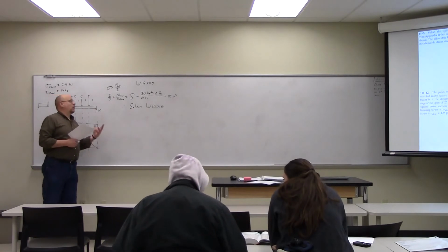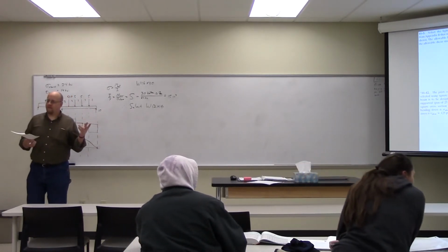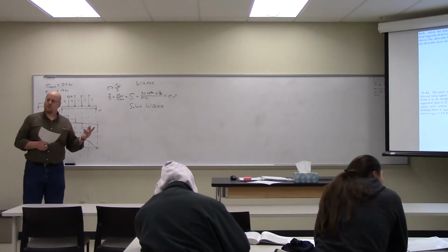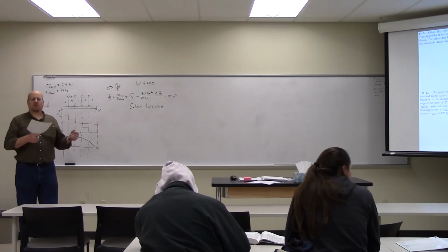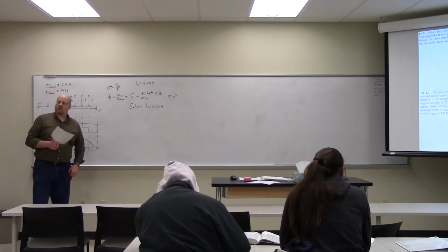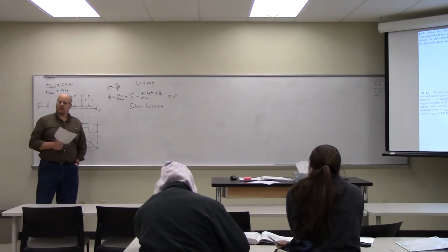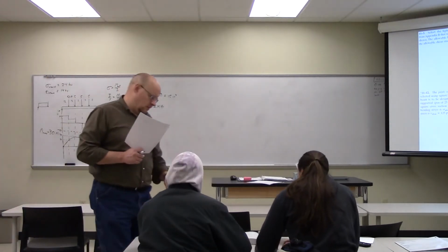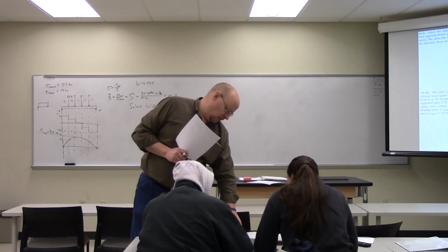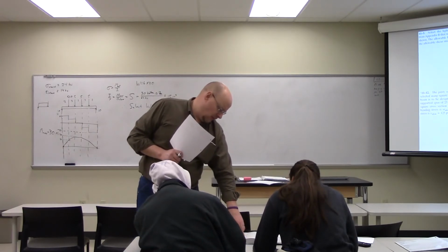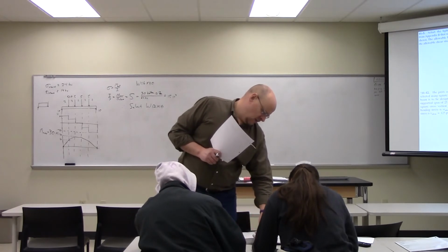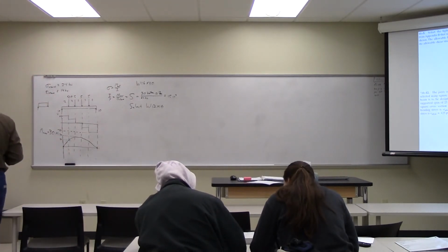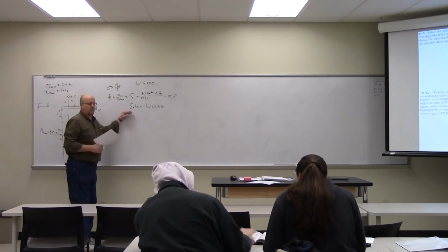Okay. So, are we done? Have we made our selection? I've got a quick question. For wide flange beams, is there a specific amount of width to the flange? It's specified for each one. Wide flange doesn't mean 6 inches or 10 inches. It's one of the tabulated values, the B value, the width. If you look in the table, you can see the widths go from 12 3/4 on the high end down to 4 inches on the small end.